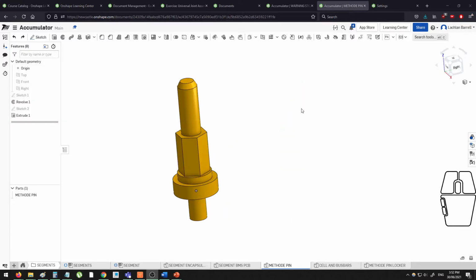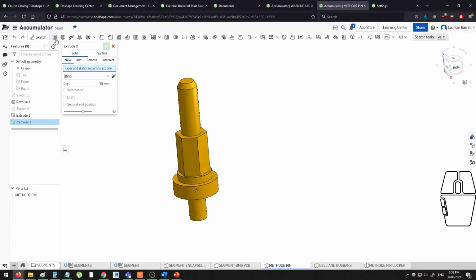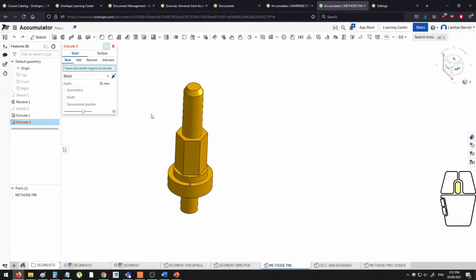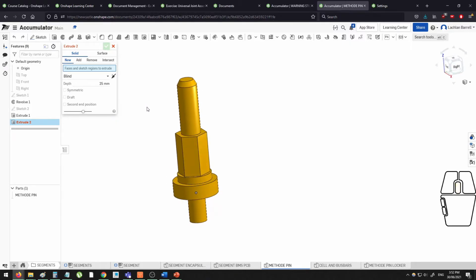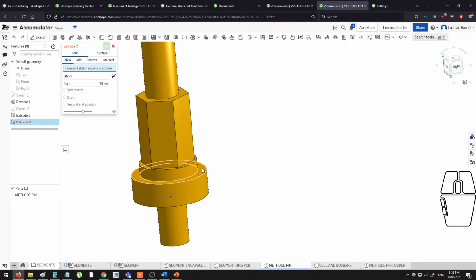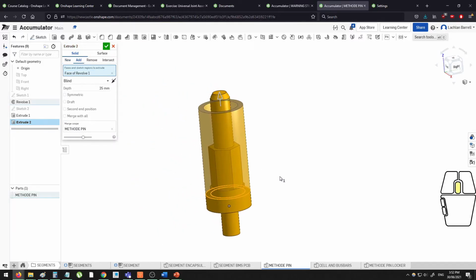So a little tip that I'll give you is that you don't actually have to extrude only from sketch faces. So I can grab a face that hasn't been defined by a sketch, such as this one down here, and I can use that as my extrusion. Right up here, we've got the Boolean options. We'll touch more on what Boolean options mean in Onshape later, but they're really important to understand, as these are basically what facilitate us to have multi-part modeling within the same part studio.